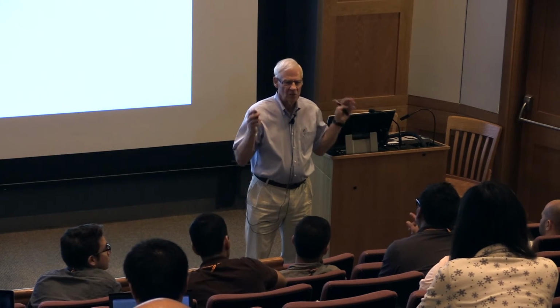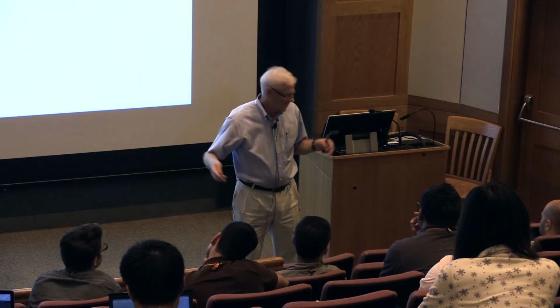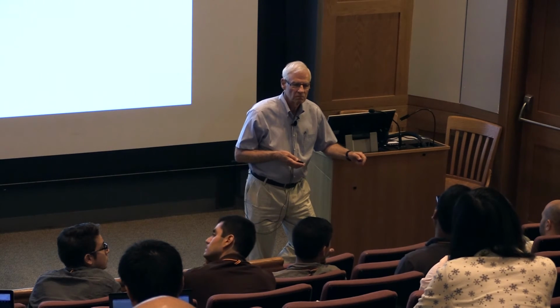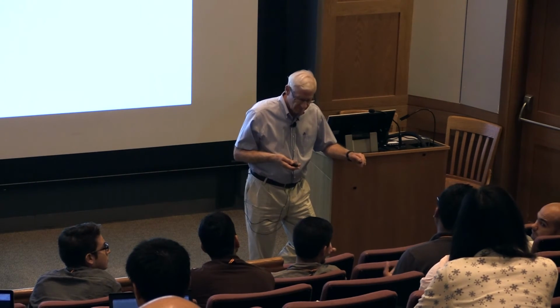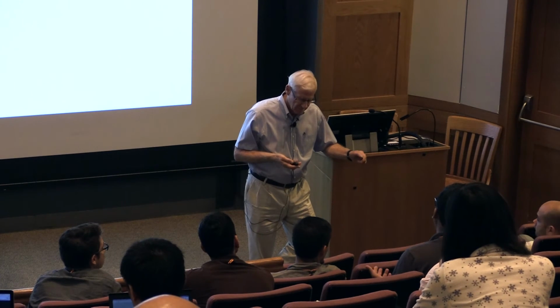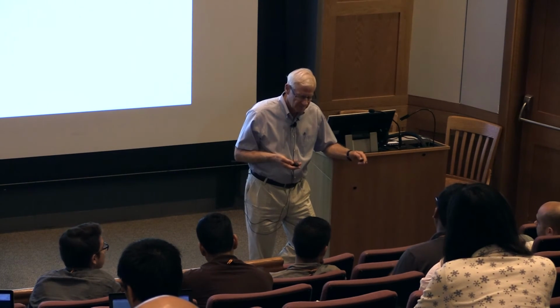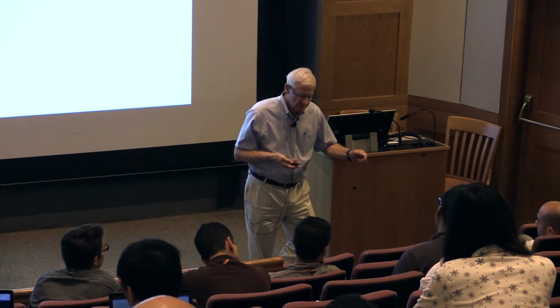Then we can do clean experiments, but the practical people want you to do it in air. That's the problem. But in that case, you cannot use the pressure time histories to see where the ignition delay time is. So my question was for using OH: are you using laser absorption or maybe emission, like chemiluminescence? We do both. Okay, gotcha.